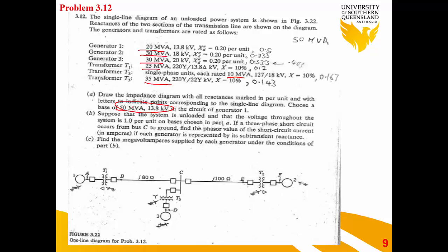So far, there are a few things you have to understand. What is the connection for the first one? Y connected with neutral. You can see the transformer is delta Y. Someone may think the little symbol doesn't matter, but it is important, especially for your assignment, and in any problem solving it will change your results.